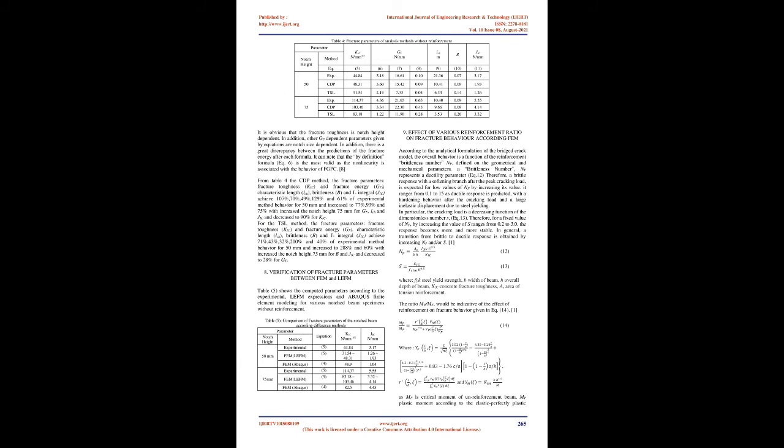It can be noted that the higher the reinforcement ratio in the samples, the less the difference between them. The average difference between the finite element methods results reduces as the reinforcement ratio increased from 0% to 0.3%. Figure 15 shows the load energy curves for 50 and 75 mm notch height with various reinforcement ratios.